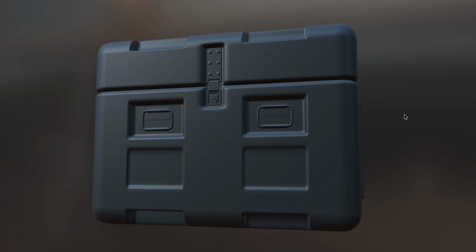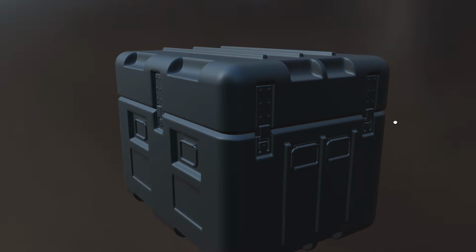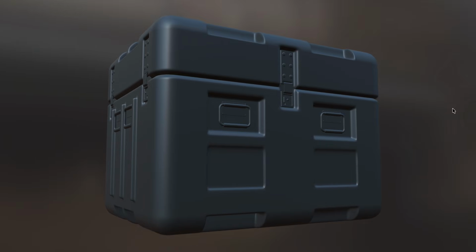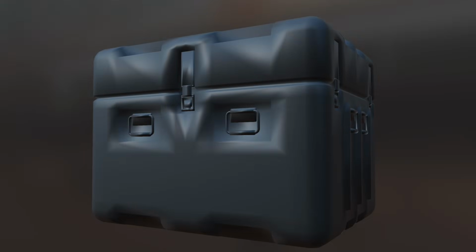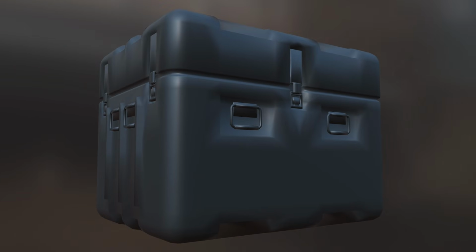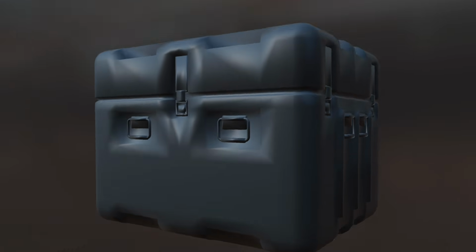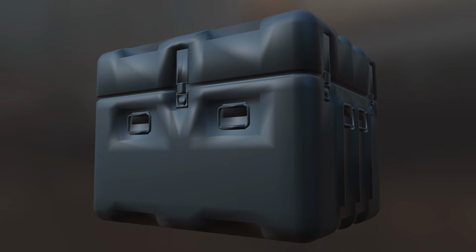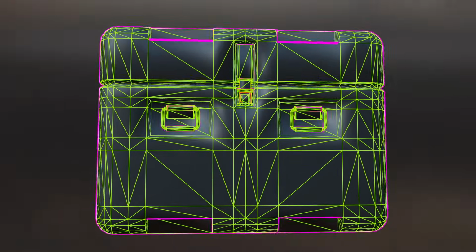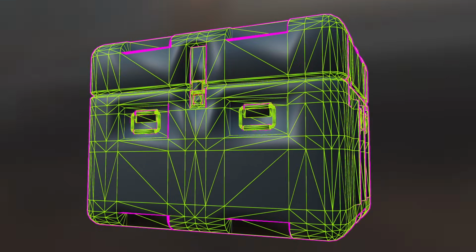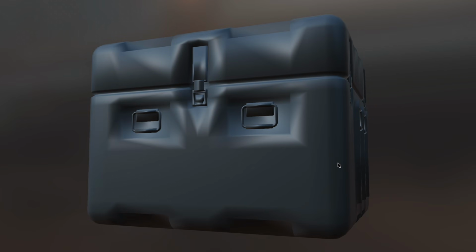This is called the high poly model because it often contains a higher amount of polygons to represent those intricate details. The target mesh is often a simplified version of that same model, usually broken down into simpler shapes. This low poly model is often constructed with the high to low baking process in mind so that it accurately captures the intricate details of the source model but represents those details using texture maps instead of modeled out geometry.